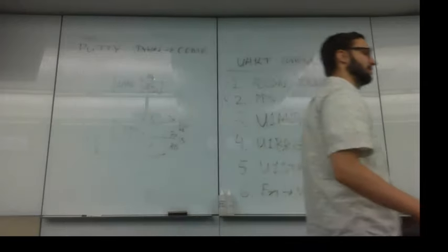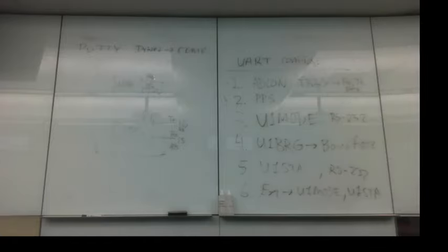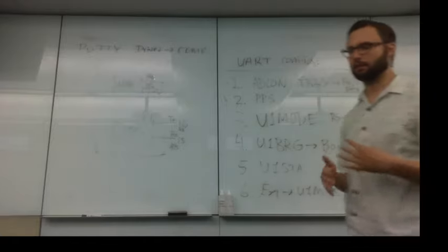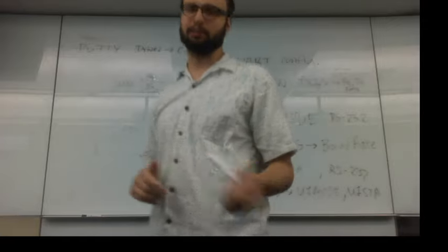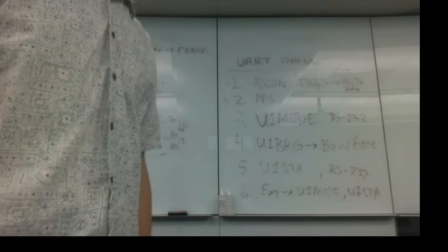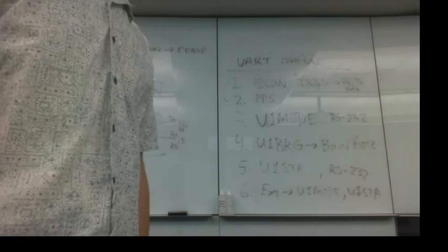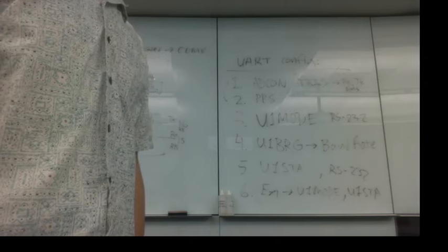A lot of times when you're configuring things, you want to disable that right off the bat to make sure that the UART isn't reading the different status and baud rate generator bits before it's ready to go. All this other stuff, FRZ, USIDL, we're not going to really use.